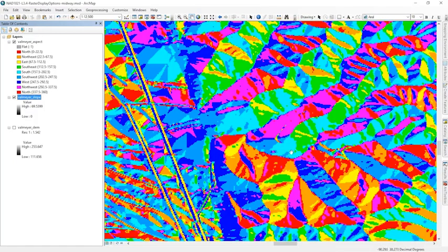And maybe I want to analyze these at the same time, or I have some aerial imagery I want to take a look at too, but it's hard to see at the same time as this data because it's so colorful. I could set it as semi-transparent in the raster display options in the properties pane, but sometimes that's a little wonky and you want to see one at a time. This is where the swipe tool comes in.